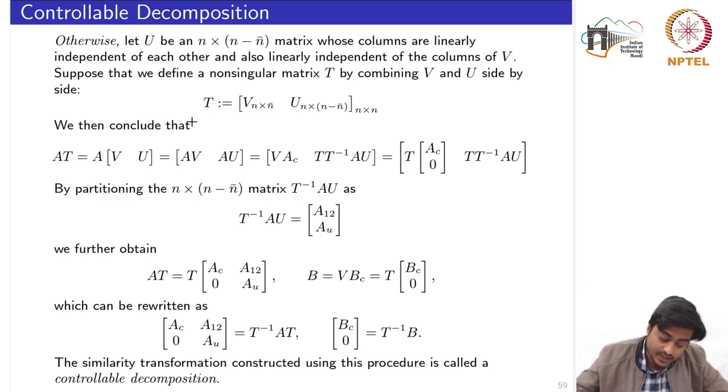So we just have constructed a T matrix given the matrices A and B. So this part is called the controllable decomposition. We will explore further properties. With introducing this specific T matrix given here, we have decomposed the A B matrices into controllable decomposition.